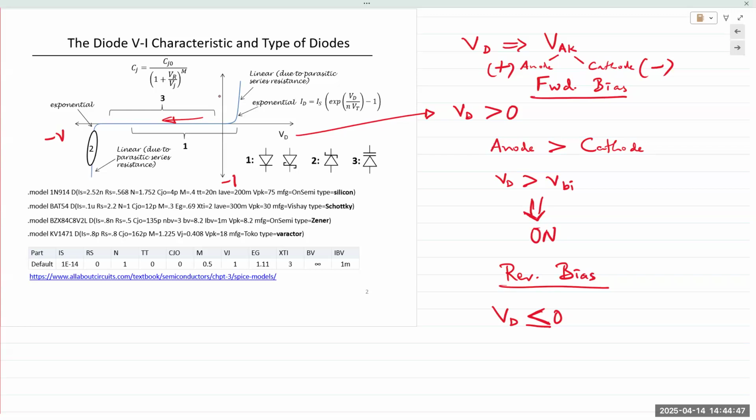Now, this current is known as the saturation current because it quickly saturates at a certain level. That level depends on the geometry of the device as well as the doping profile of the semiconductor. Typically, the saturation current is on the order of nanoamps and picoamps, so small that we can't even measure it, and it remains pretty constant. If you try to measure this in the lab, all you will see is 0. You won't see anything else.